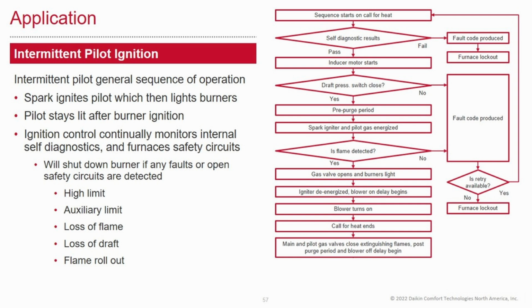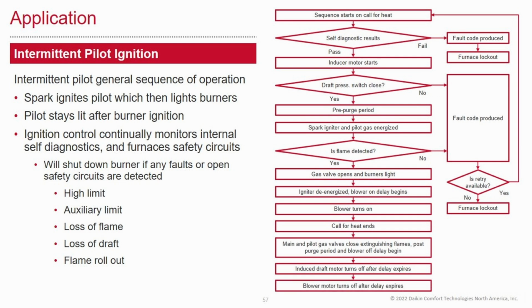After the post-purge period expires, the inducer draft motor shuts down and the blower-off delay begins. And then the blower turns off after the blower-off delay expires.